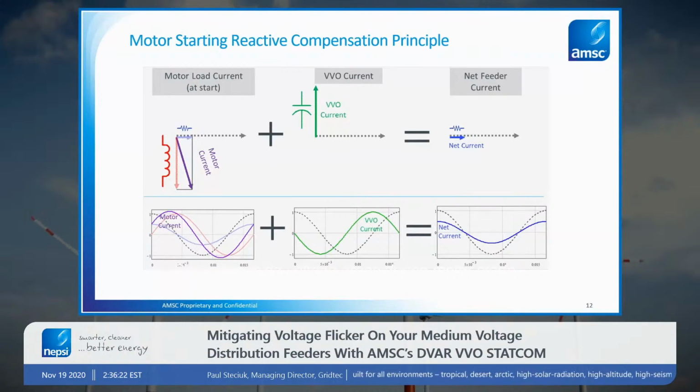And that real power, as we showed early on, is typically not going to cause a power quality problem. So it's usually a lot less than the reactive current. And then, of course, the feeder resistance is typically not a significant factor in terms of causing voltage drop.